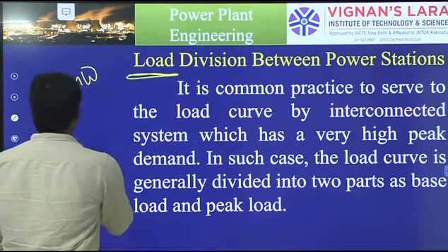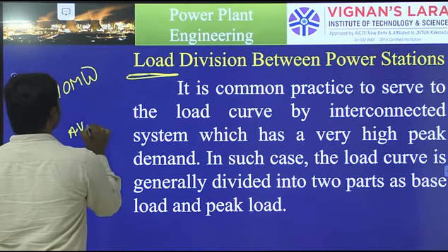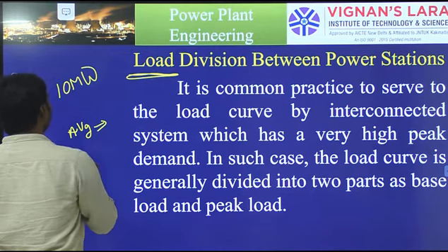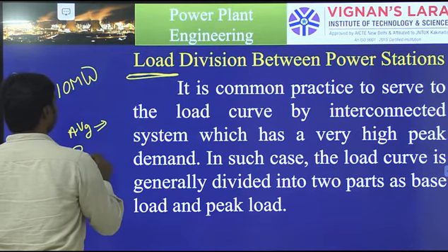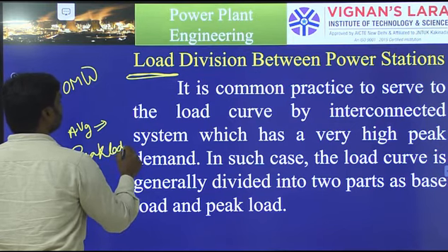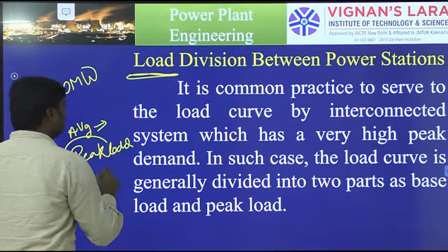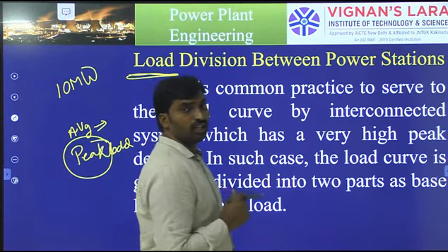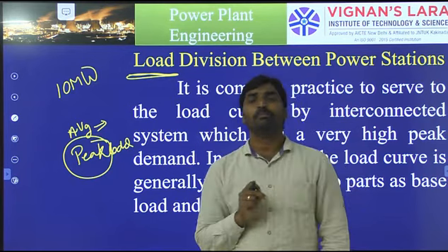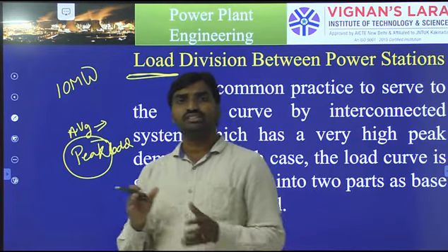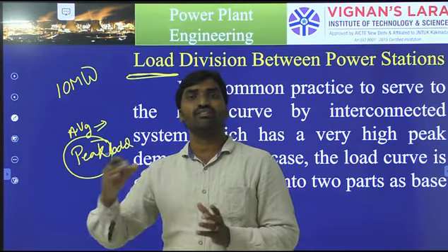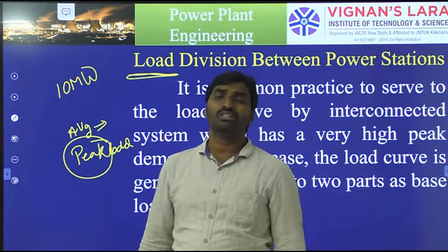Okay, so that's an average power required for a day. But in case of a peak load, the second term is peak load. Peak load means the maximum load at a particular time. Generally, in a single day, the peak hours are some morning 10 to 12 or evening 5 to 7. So these timings are generally known as the peak hours.